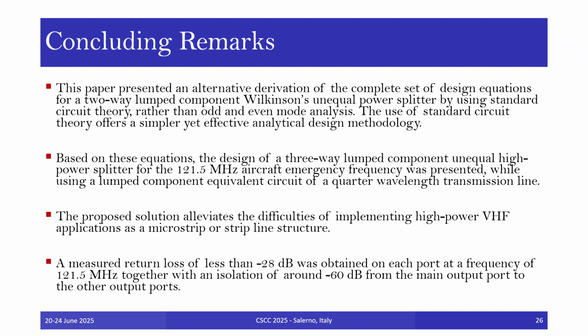This work presented an alternative derivation of the complete set of design equations for a two-way lumped component Wilkinson unequal power splitter by using standard circuit theory, rather than odd and even mode analysis. The use of standard circuit theory offers a simpler yet effective analytical design methodology. Based on these equations, the design of a three-way lumped component unequal high power splitter for the 1 to 1.5 MHz aircraft emergency frequency was presented, while using a lumped component equivalent circuit of a quarter wavelength transmission line.